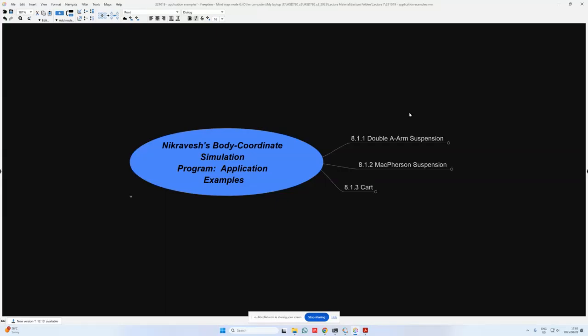So you'll remember that the wheel assembly actually moved downwards to make contact with the ground. The fact that it moves down is due to the weight or gravitational effects pulling the wheel assembly down. And we activated weight on all of the bodies. So that means once I start reducing the bodies, the mass and moment of inertia effect will also be felt on the kinematics of the system.